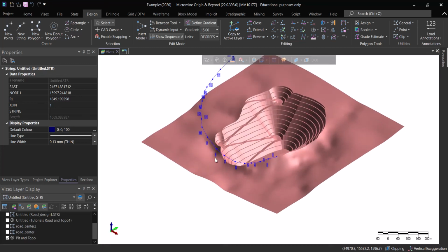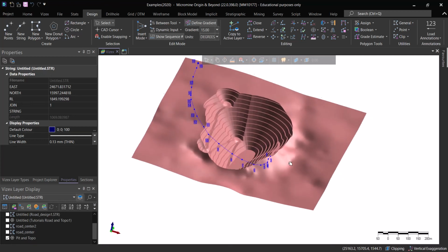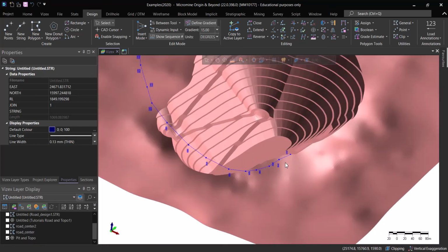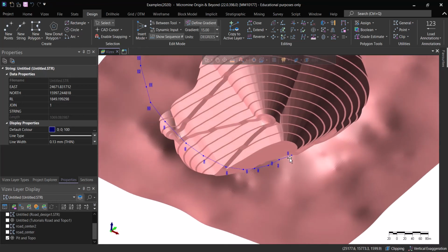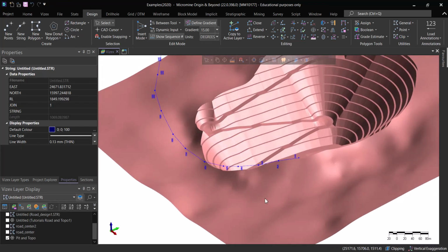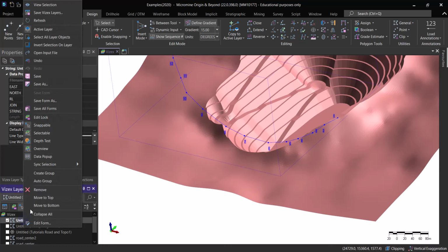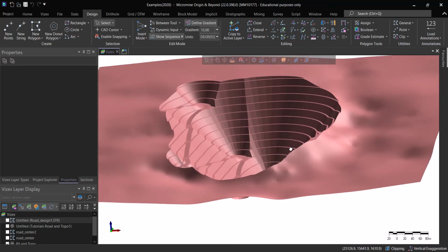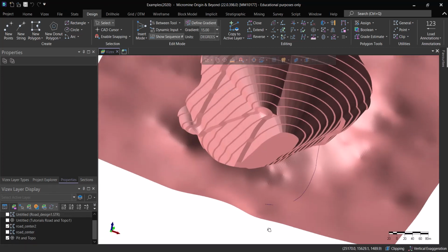So what we can do with this method is digitize, let's say, a center line, but this time without dropping it on the topography. We are going to assign a constant slope, or maybe we can change slopes whatever we want. Like I said, we started with 20 degrees in here because it's very steep, and maybe we can use like 5 degrees in here to make this road design. So let me go and remove this one, and I don't want to save that. That was just to show you how to make a constant slope string, and this is exactly what I've done with this one here.